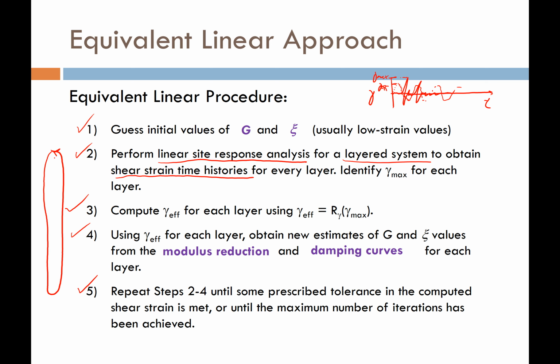steps 2 through 5 until I converge on values of modulus and damping. They're not going to change anymore. Once I converge, then I know I have a solution.